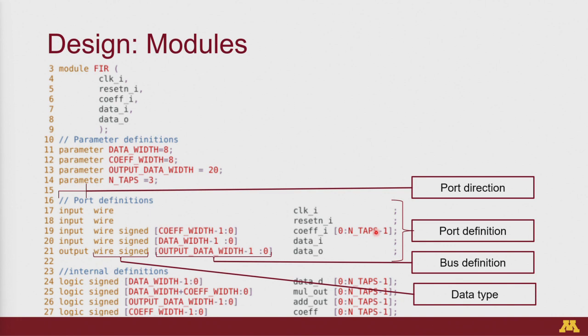If it's before the name, we call these packed dimensions, and if it's after the name, we call it unpacked dimensions. Now, what is the physical significance of a packed dimension versus an unpacked dimension? The way you think of it is that packed dimensions are those dimensions which are logically together like a bus. For example, if you're working on a breadboard, think of a bus of wires all working as an entire set and not as individual wires themselves. You've seen those multicolored rainbow buses which you can connect, right? That's what you think of as a packed dimension.